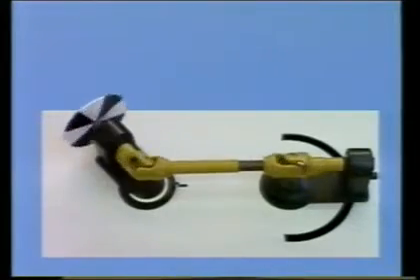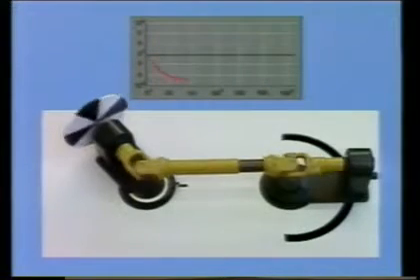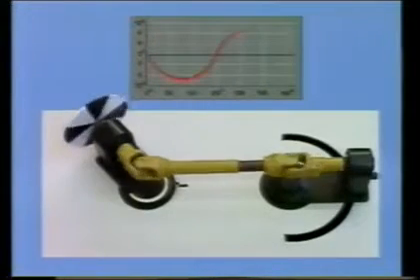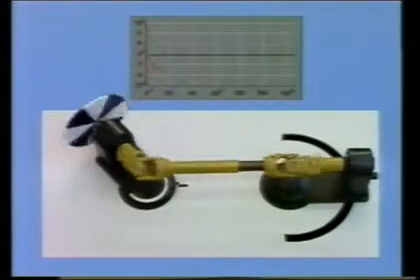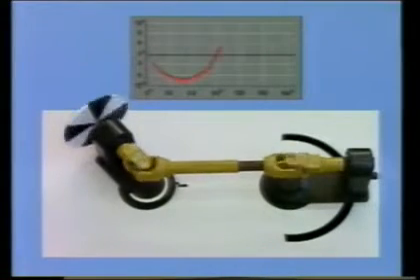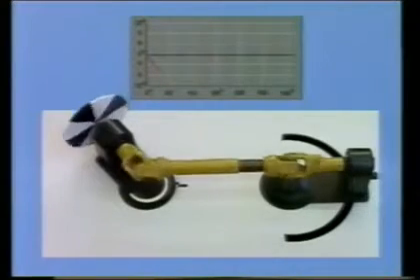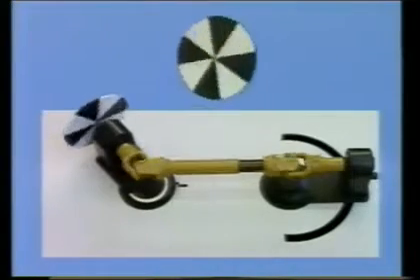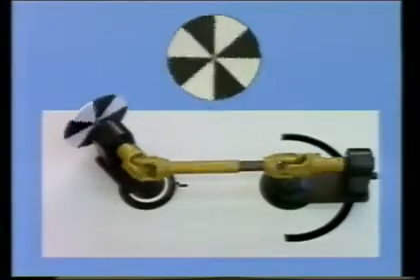The prerequisite for uniform rotary motion with a PTO drive shaft is that both outer yokes and both inner yokes are in one plane. With Walterscheid telescoping profiles, this prerequisite is always fulfilled. Any other arrangement of the joints in relation to one another is wrong and leads to non-uniform rotary motion at working angles.